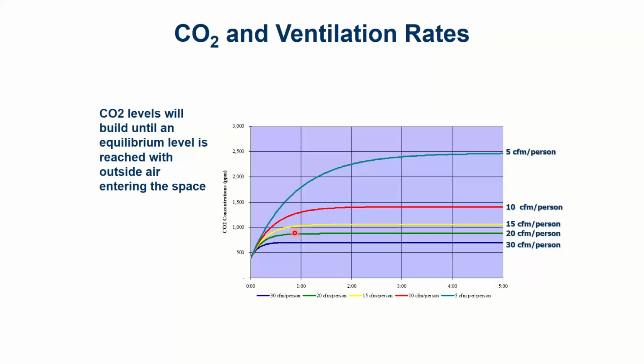And then later on, people are leaving the conference room and I see the CO2 level dropping down. I start closing the ventilation rate back. It happens in real time. It's not an open closed damper. It modulates based on how much CO2 is in the space.